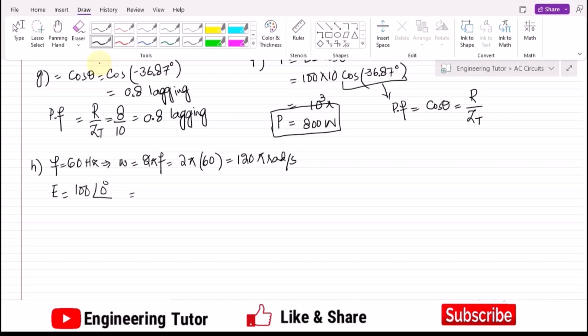So converting the RMS value into the peak value, I have to multiply with square root of 2, and after it the sine of omega t plus theta. So omega is already known, and that is 120 pi t, and the angle it has is 0 degrees. So that's it.